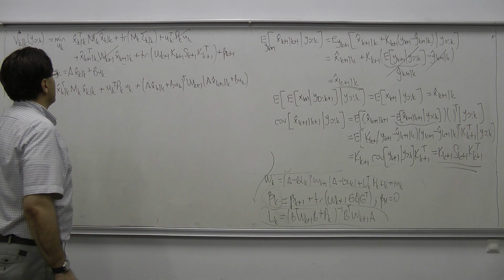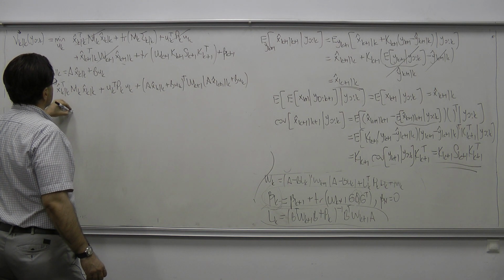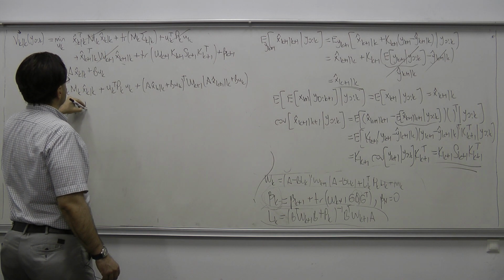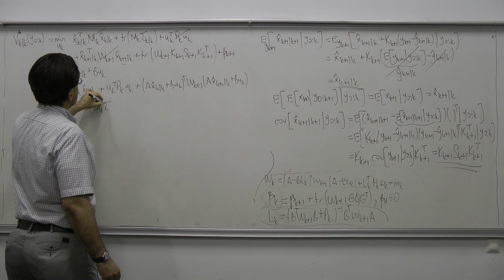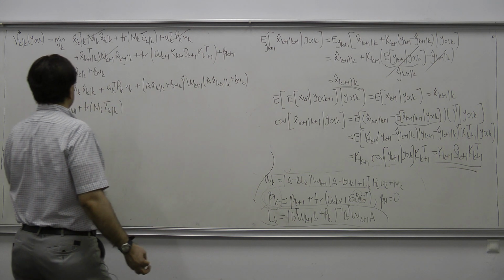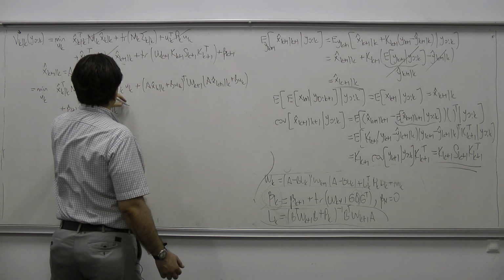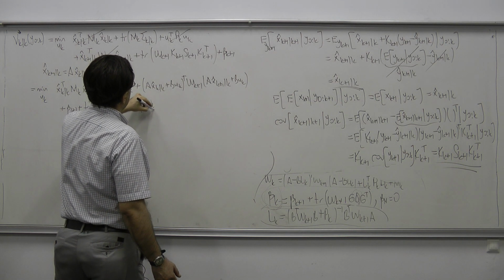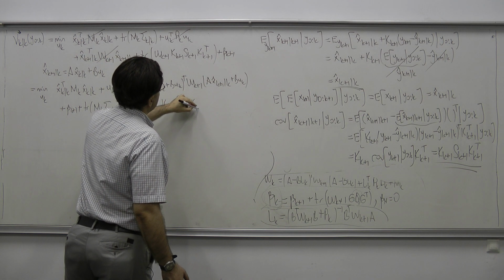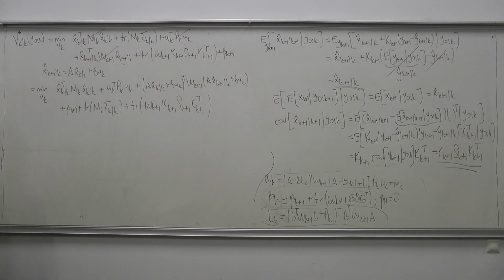And now I'm going to add the other terms. I have beta k plus 1, and I have here trace Mk Sigma k given k. This is independent of measurements because it's only dependent on covariances of the Kalman filter. And I would have this term plus trace W k plus 1 K k plus 1 S k plus 1 K k plus 1 transpose, and that's it.